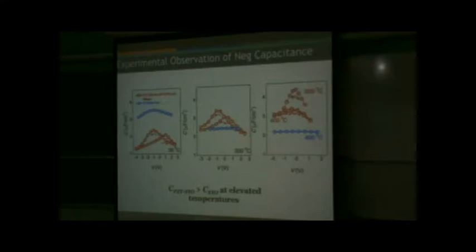The capacitance is much below STO. I do not see negative capacitance. Okay? I increase temperature. You see that now this 76 nanometer thick heterostructure gives me higher capacitance compared to the 48 nanometer STO. Okay? And so this means that I am seeing the negative capacitance now. But I still see hysteresis.